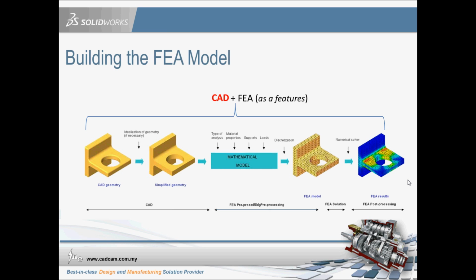With any design change, the setup will immediately update and you just rerun to get a new set of data. It saves you tremendous time on moving the parts out and resetting all the finite element setup again and again. So this is what we would like to share, and we hope you accept that this is one of the good features for you to design better products.